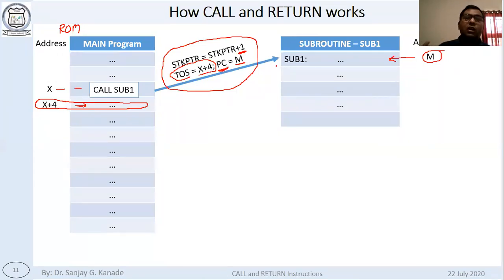The microcontroller executes the instruction at the address given in PC. As usual, PC always holds the address of the next instruction to be executed. Now the contents of PC is M, so whatever instruction is written here, that will be executed next. Means after call, this particular instruction will be executed.